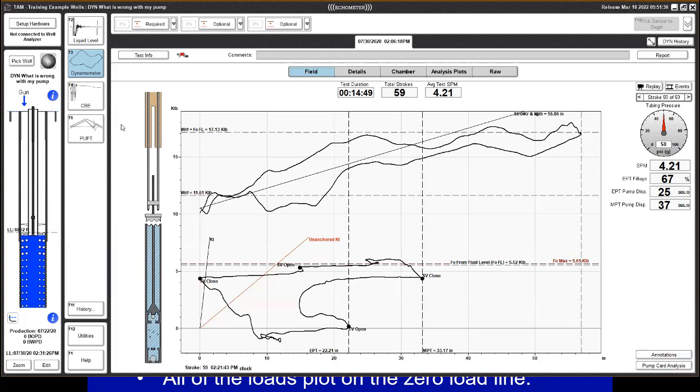When you have a controller, you have a load cell giving you load, and from a different sensor, a Hall effect switch or an inclinometer or potentiometer or some other source of information, you have the position. Then that position and load have to be matched, and sometimes they are not in sync, which gives you, for example, a top of stroke problem where the dynamometer card slants to the right or the left and starts giving you weird, unrealistic pump card shapes. It doesn't show good pump tagging down. So no, loads or dynamometer cards from a controller are not compatible with Echometer technology.